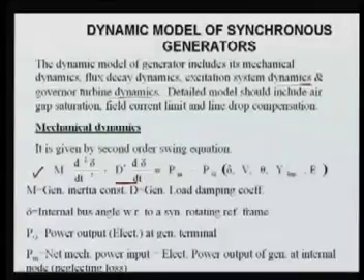In the previous case, we ignored this and then solved the dynamic equation, that is the swing equation of the machine. This is basically mechanical dynamics, because here the angle and the machine's inertia constant, etc. are included. So now in the practical transient stability program, this is also taken into account, and it has a big impact on transient stability and other stability considerations.